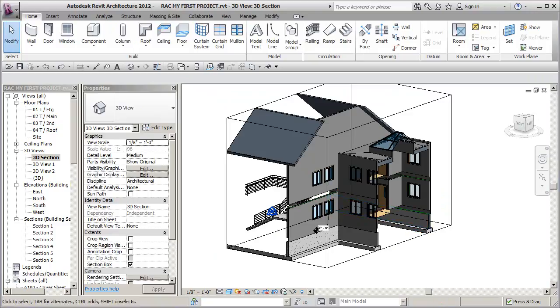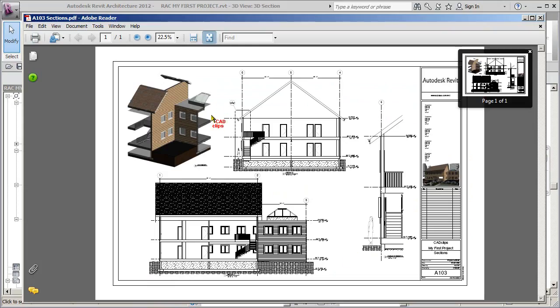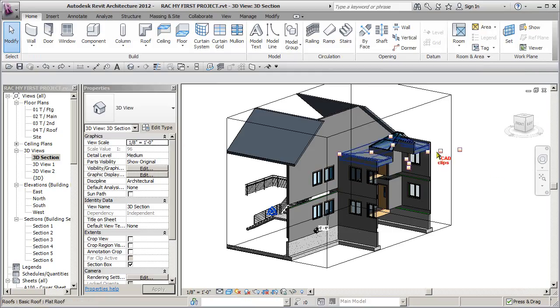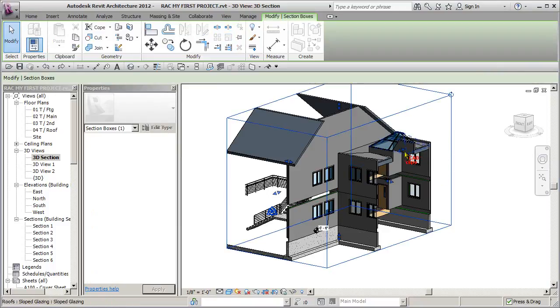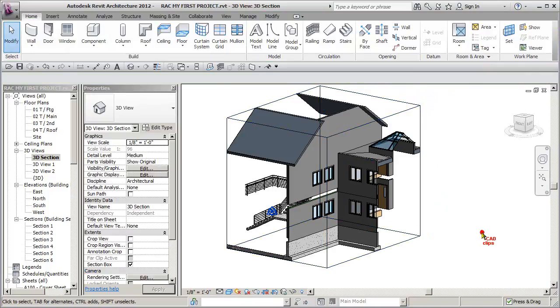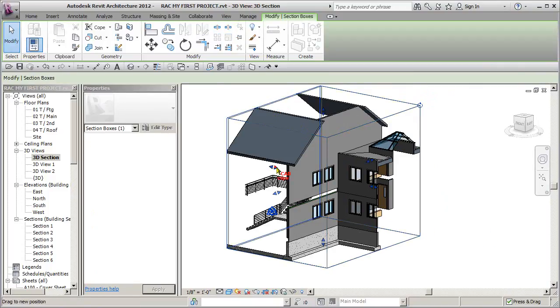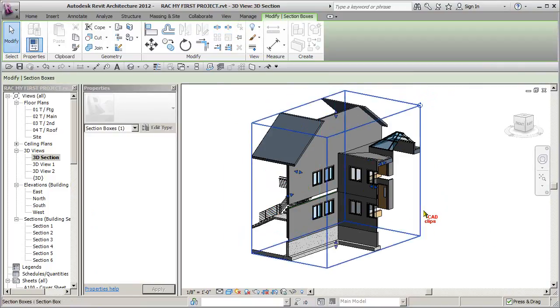Click and undo. And let's have another look at our 3D section here. Are we clipping through? Yes, we are clipping through the black. We're clipping through here. We're also set to be realistic visibility, which we'll get to a little bit later. So I just need to clip my back. So that goes through there. And I'm going to bring this forward a little bit.